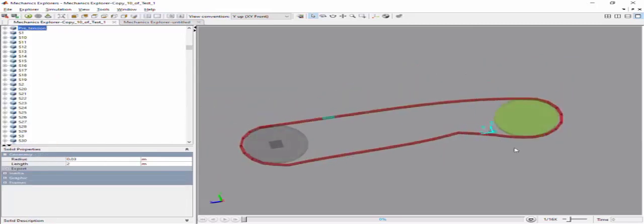As you can see, and I already talked about this matter, the belt material around the pulleys is not under tension at the very moment. Just before we start exerting some torque to our pulleys, and just before we start the belt conveyor, we need the belt material to have some friction against the pulleys, so that when we rotate the pulleys, the belt also starts moving.